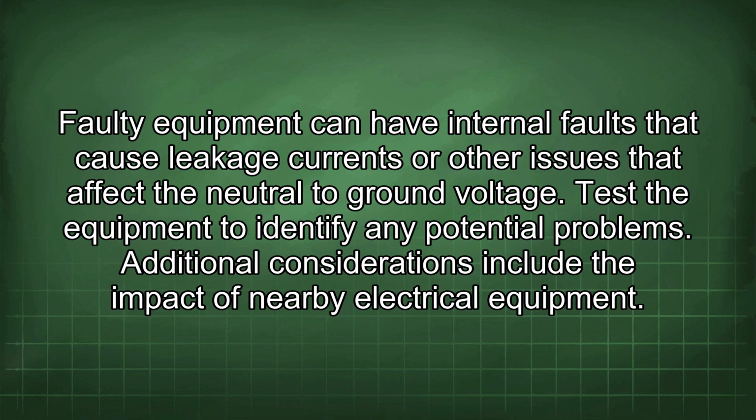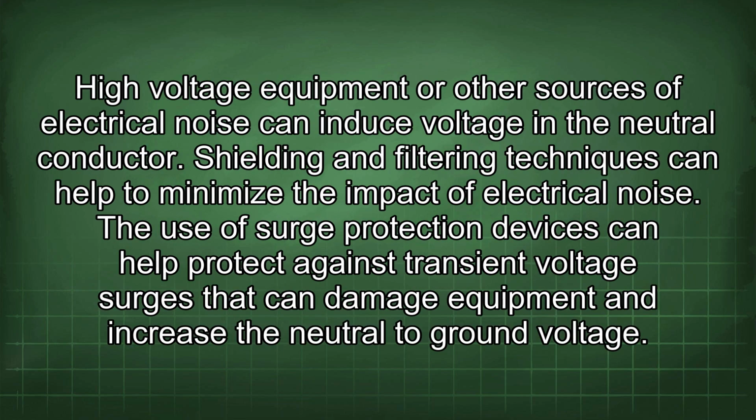Additional considerations include the impact of nearby electrical equipment. High voltage equipment or other sources of electrical noise can induce voltage in the neutral conductor. Shielding and filtering techniques can help to minimize the impact of electrical noise.